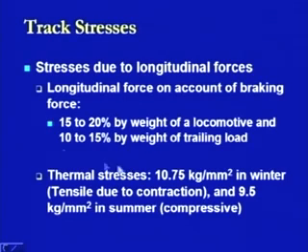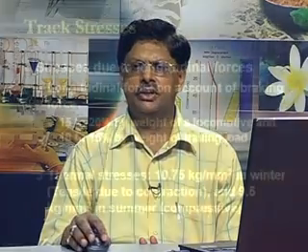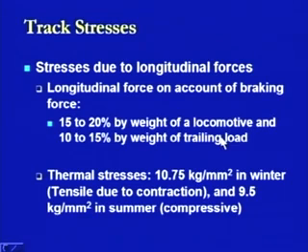Similarly, if we look at the stresses or the forces which are induced in the longitudinal direction on account of braking or the application of the brakes, then that is going to be different for different conditions, because we have the locomotive, and at the same time there are trailing units in terms of the wagons which are attached to the locomotive. So it is a little different: it is 15 to 20% by weight of a locomotive, whereas in the case of the trailing load, which is nothing but the wagons, maybe the passenger wagons or the freight wagons being attached to the locomotive, it is 10 to 15% by weight.